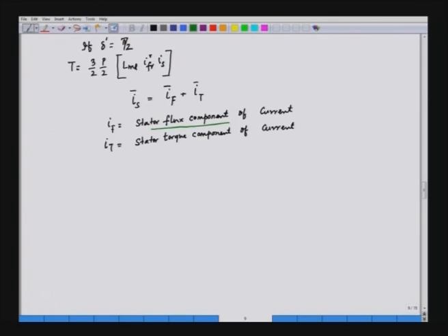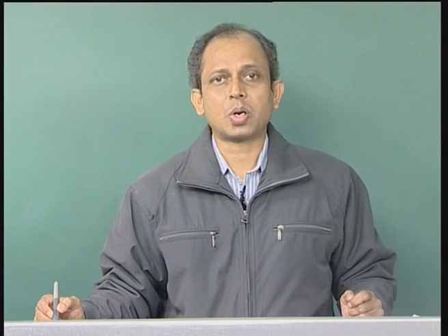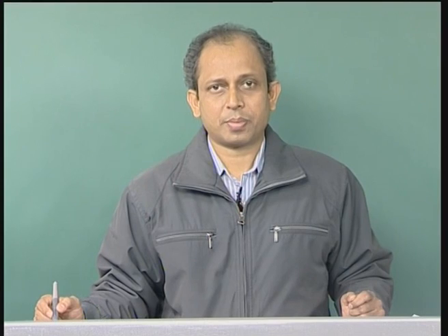And the torque is usually controlled by controlling I T, and that is why this is called the torque component of current. So, in general we can have a block diagram, and the block diagram will explain the various control aspects of the vector control of PMSM drive.